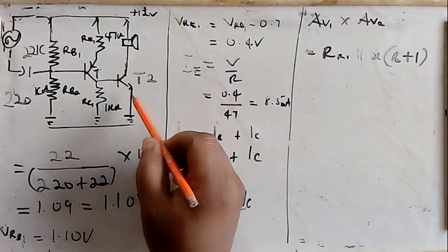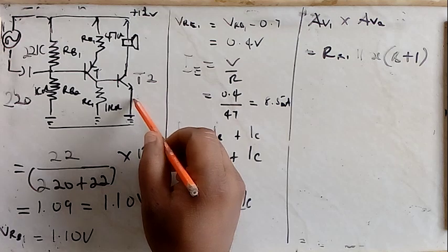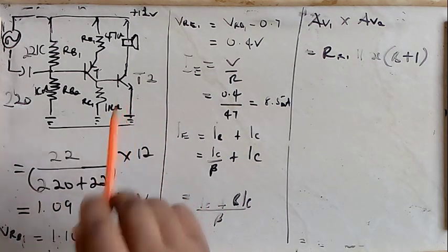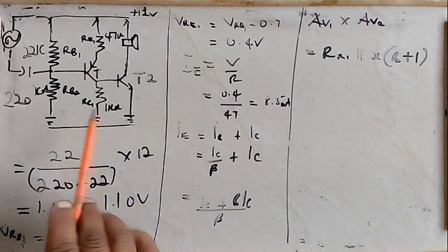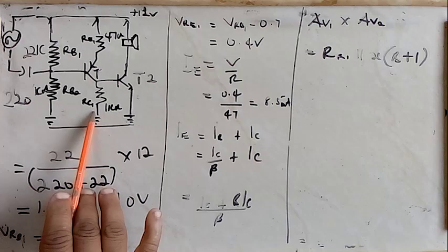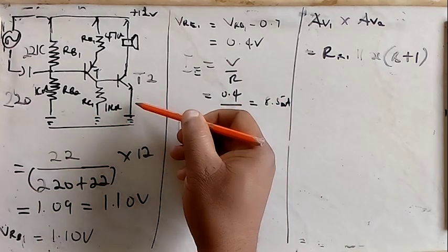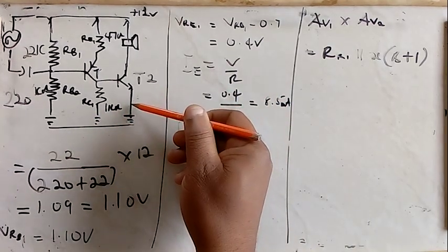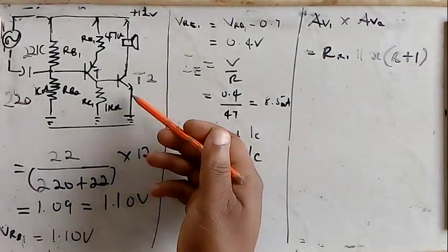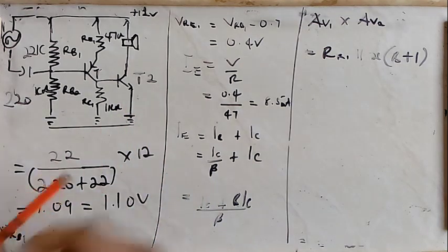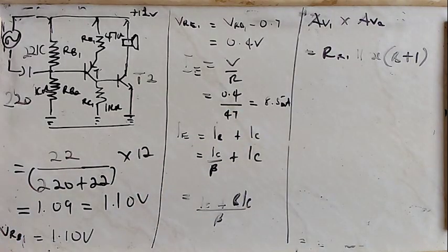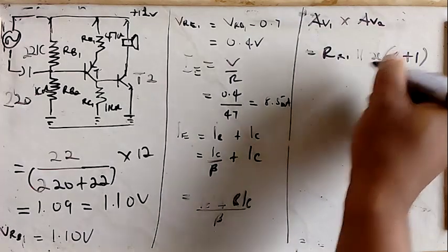Now, because of the design of the amplifier, there's no emitter resistor here. So it renders the amplifier unpredictable. If there were an emitter resistor here, this voltage here will be guaranteed, and it will lead us to establish easily the voltage in the emitter resistor here. So either we'll break the circuit up, put our multimeter there, or for purposes of simplicity of our analysis, we assume that the current being passed here is 4 milliamperes.